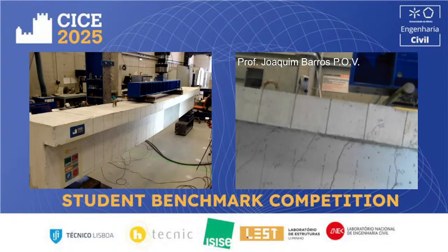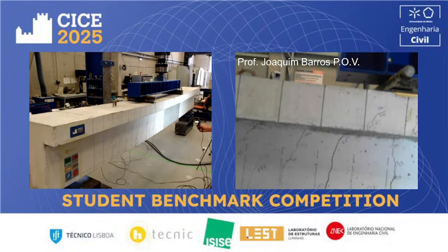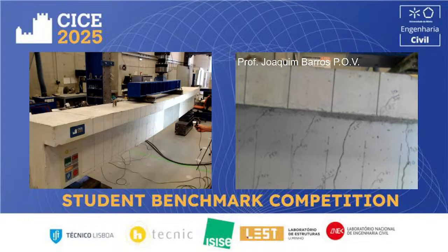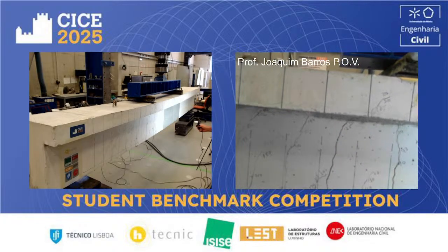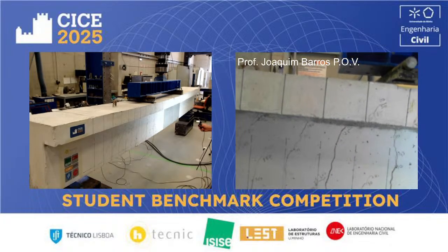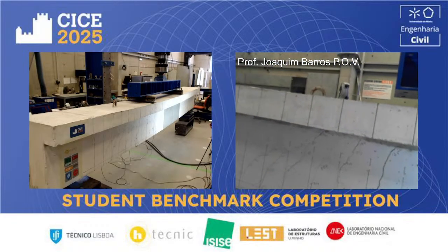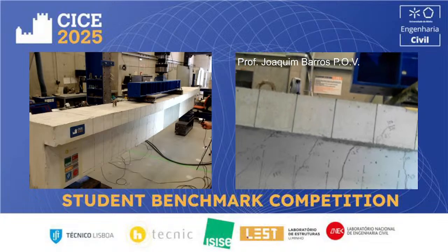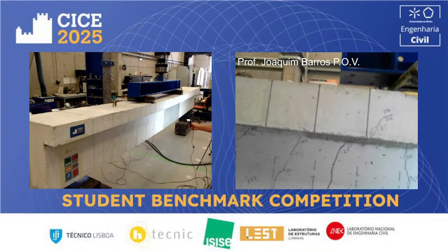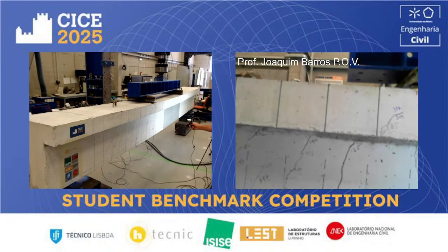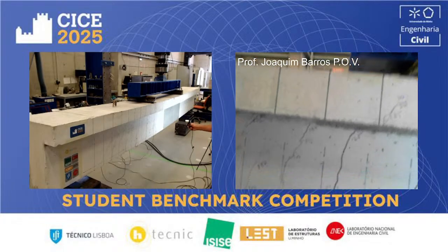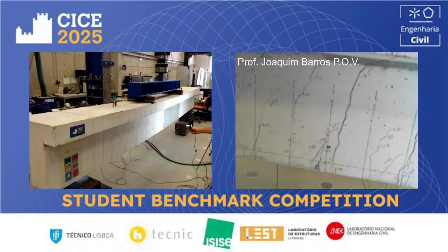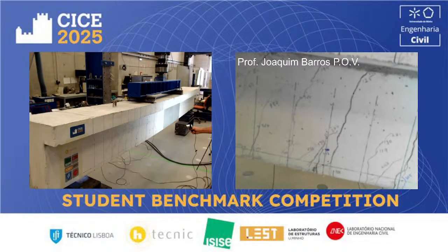Okay, so look at the evolution of crack width in this crack from the bottom to the top. Closer to the loaded section, but localized in the shear span, the crack width is very large. I don't have any doubt it's more than 2 millimeters at this moment in the middle, but at the bottom, when crossing the reinforcement, the crack width is much smaller.